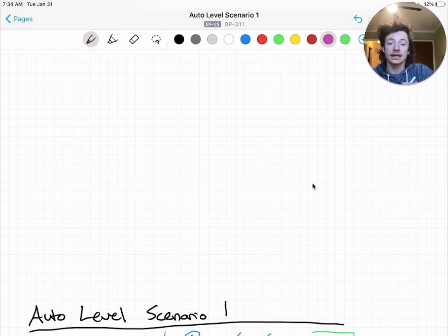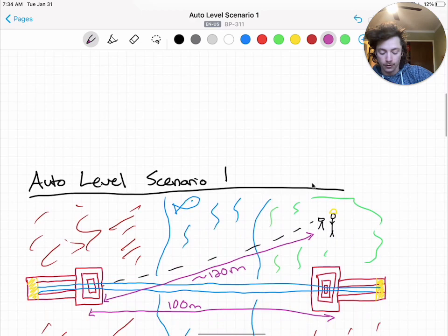It's time to hoist the cables, so you mark the F values for each cable position onto the abutments. You're training the auto level on the first of these values from a nice flat area on the other side of the river. From here, you'll easily be able to view the cables for hoisting and pan over to the marks on the tiers.